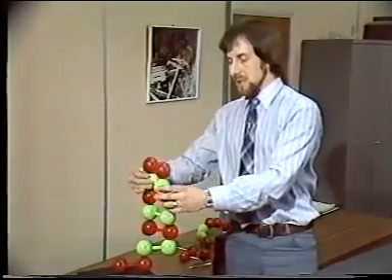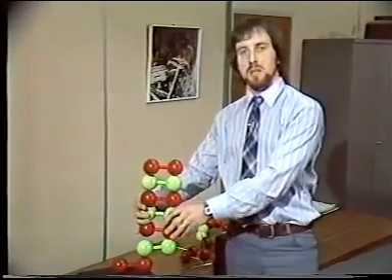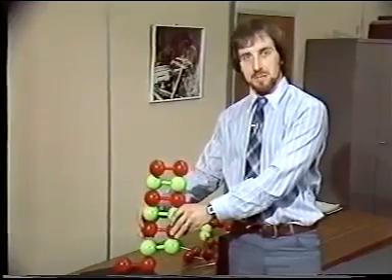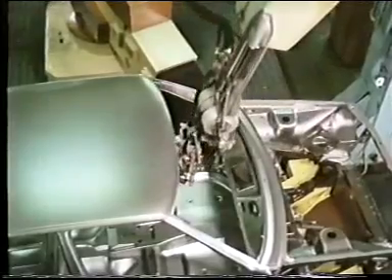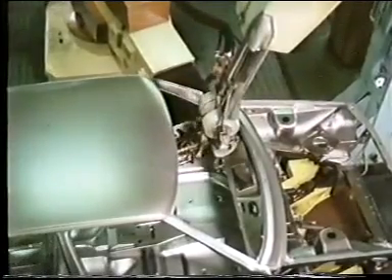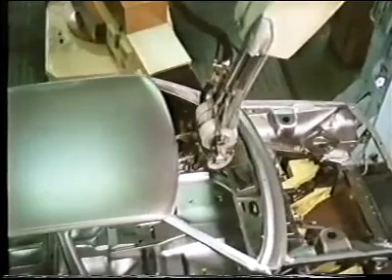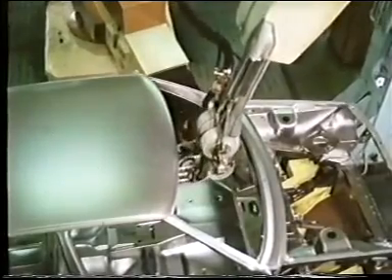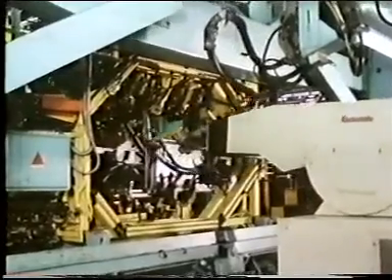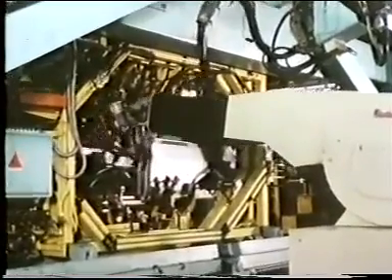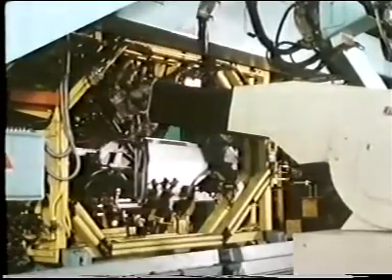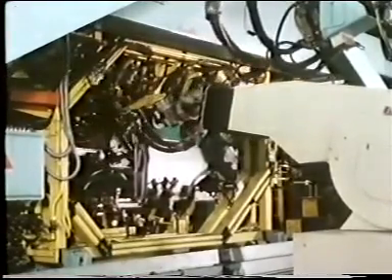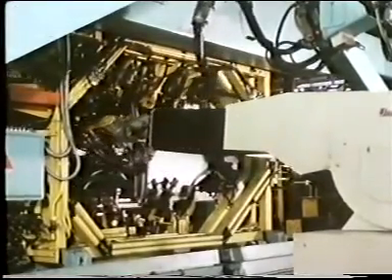What relevance does this kinematic structure and special geometry have to a real system? It's one thing to get a welding gun into a particular position and orientation, but usually it has to negotiate obstructions as well. Now, how far a particular arm can work round obstructions and reach inside things is what we call its flexibility. And it's this aspect of manipulation we want to look at now.